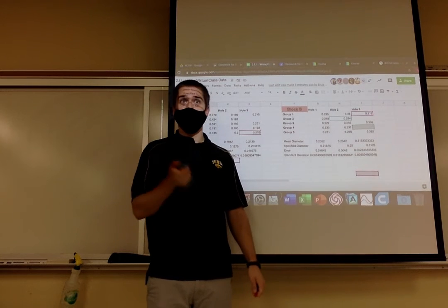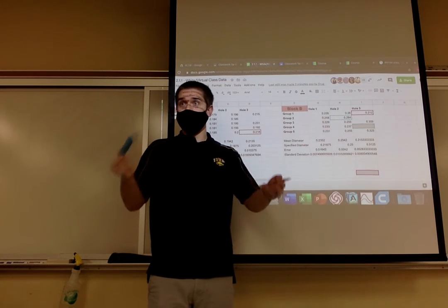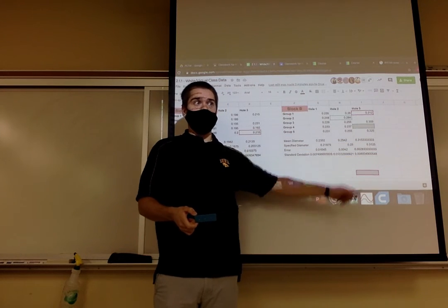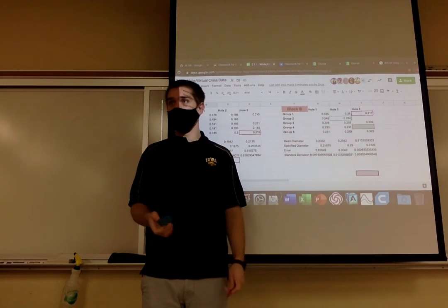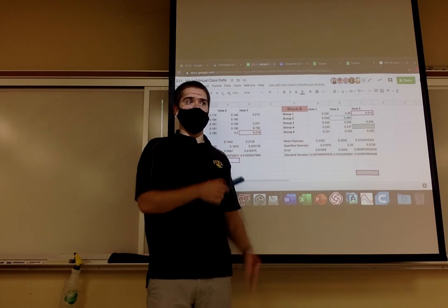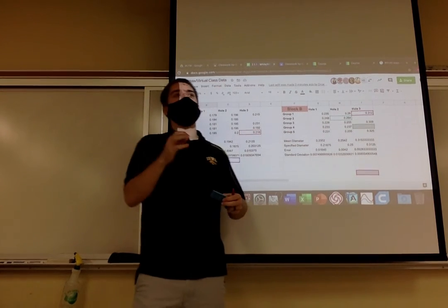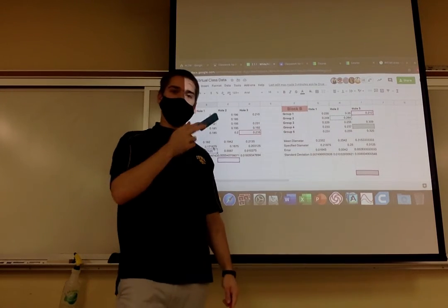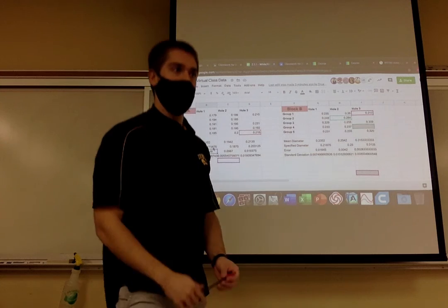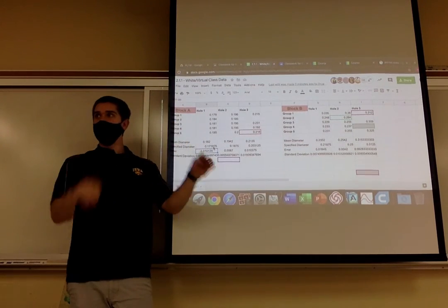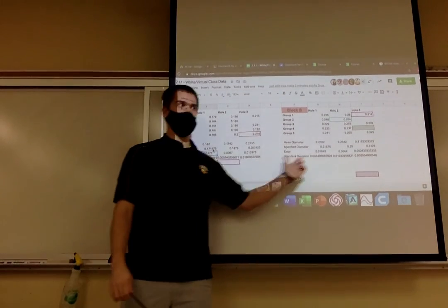That's the problem with the production line. They got their tools and they're going to use their tools, but they don't work to perfection. That's not how the world works. So you have to figure out how much tolerance can I give them so that they can make my part and it still will work properly. So that's what I wanted to show you by actually making a part, seeing if it matches what it should be, and understanding that variation happens.